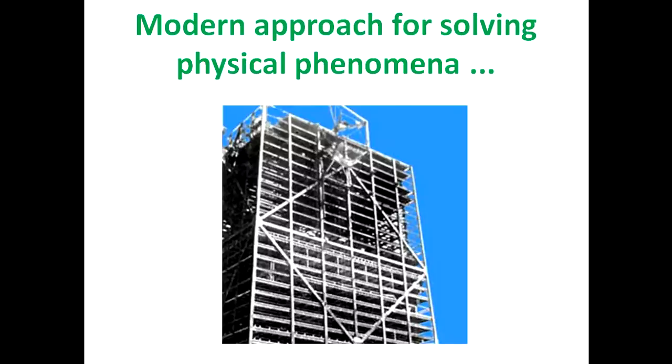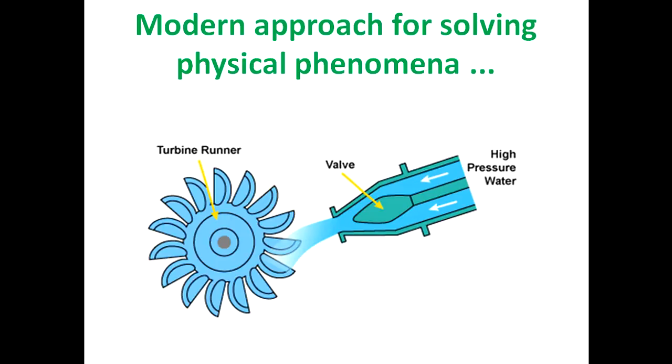We can see this feature over here. This is a simple Pelton wheel turbine which is used to generate hydroelectricity from the conversion of kinetic energy of water into the mechanical energy of the turbine. Ultimately we get the electricity by the use of a generator. So the basic idea here is that the overall efficiency of the turbine and the output power are dependent on the energy of water, and the energy of water is dependent on its pressure, its density, its velocity, and its temperature.